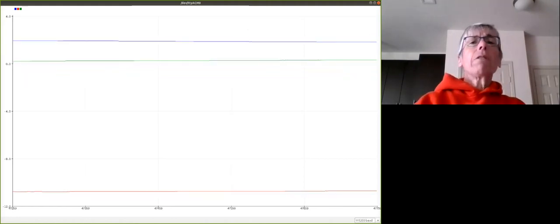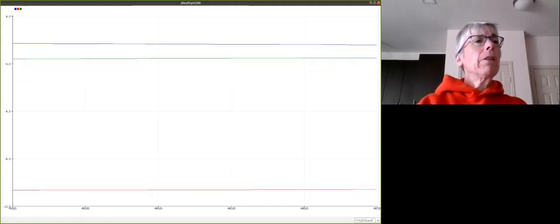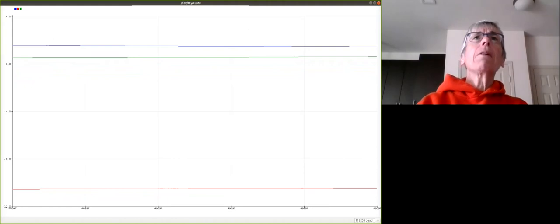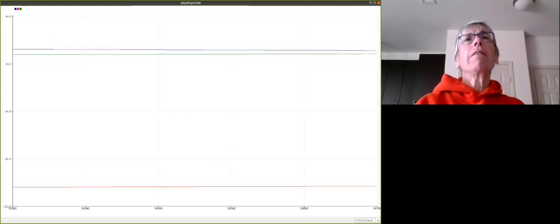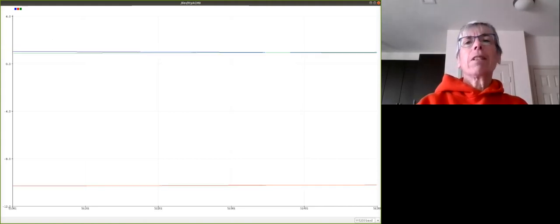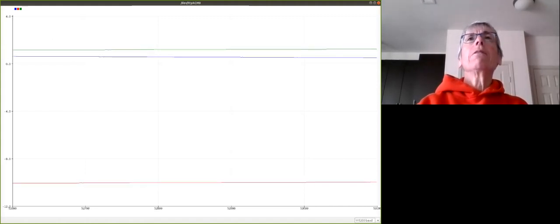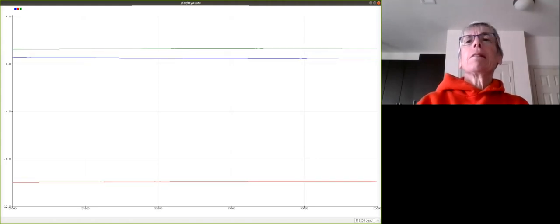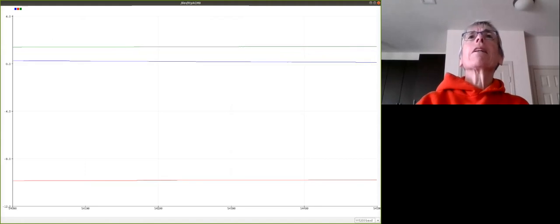Those are the drift errors. So that's just what I wanted you to see. Run that sketch, play with it. You can see those drift errors in the gyro. Next, you'll want to read the lesson on the complementary filter, lesson 11, and we're going to put that all together to see if we can get better orientation angles out of the gyro and accelerometer. So I'll see you in the next lesson as soon as I can get the menu back.